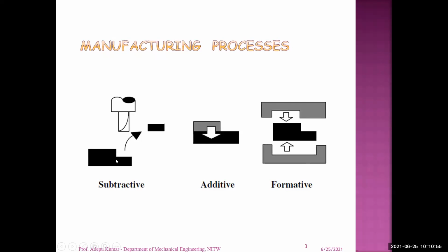So this is my final object using a subtractive process. That is removal of material from the stock using any conventional or unconventional machining process that gives your product its dimensions. So that comes under subtractive process. In subtractive process, the volume of the material is not the same before and after the process. After the process, the volume of the material is reduced compared to before the process. Whereas coming to the formative process, I can take any forming process with the help of a die. Then I can push the material through a die so that I get this shape.